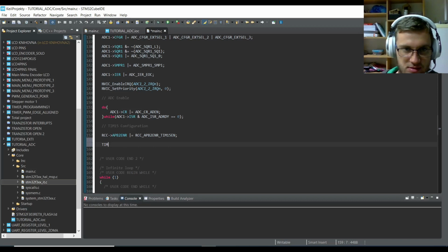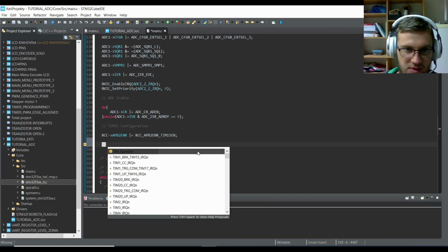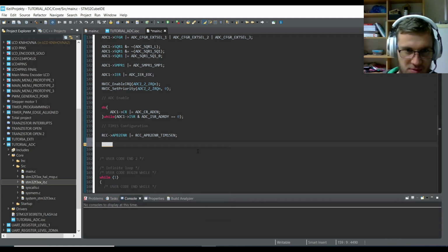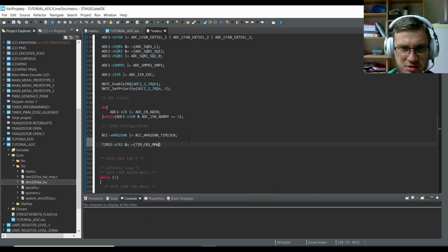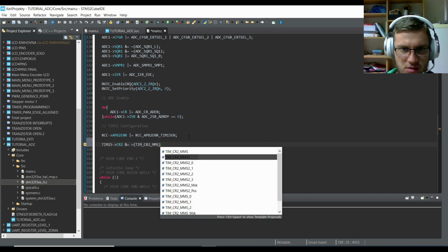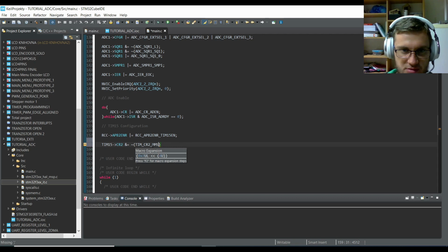It's timer 15 CR2. I will at first null all the 3 bits. CR2 master mode selection, and we actually want to set all of them to 1. Okay.